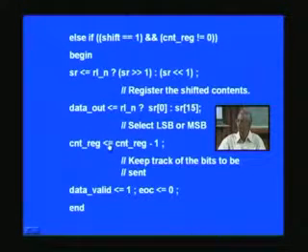And one more thing we had to do is this data we are going to send right here. That means we should also send a data valid signal here. That is what is being sent here. And since end of conversion is not really over, because there may be more bits to be sent, we still deassert that.